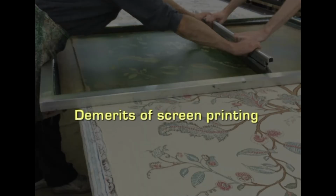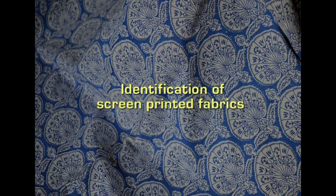Coming to the demerits of screen printing, for higher production, a large number of tables have to be used requiring huge spaces. Delicate shades and gradation of colors are difficult to obtain by this method. The process is slower than the machine roller printing. Coming to the identification of screen printed fabrics, flatbed screen prints do not have the fine line details that are possible with roller printing and rotary screen printing.